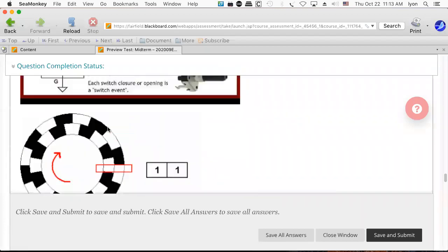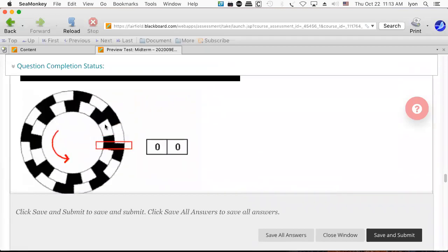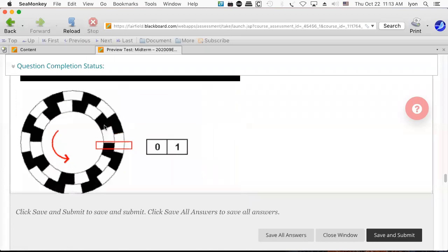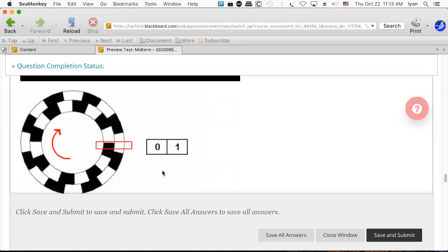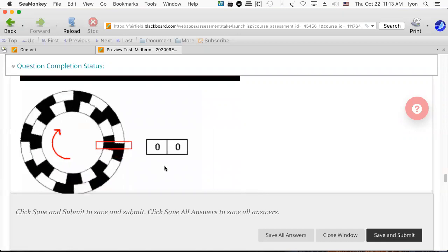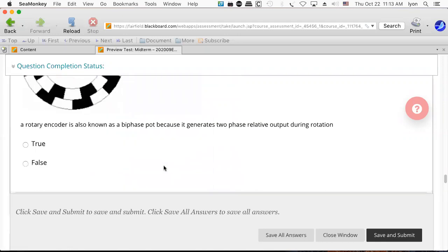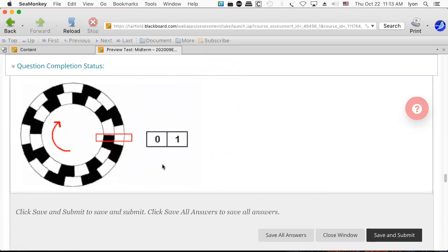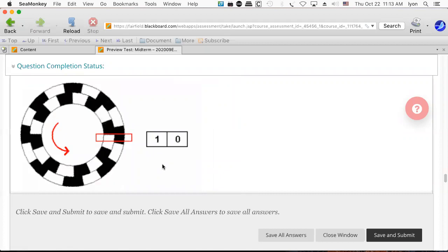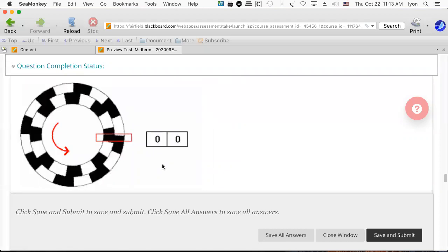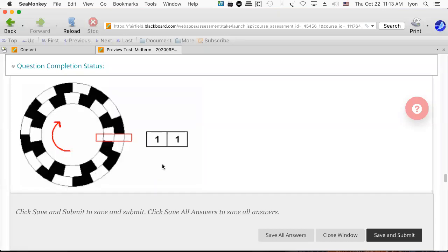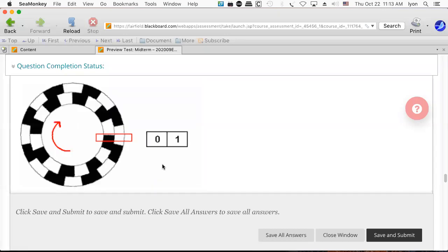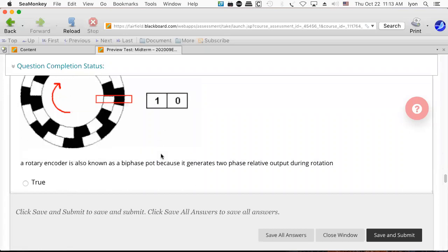And that lets you determine how many rotations you've had, or you could even be more precise and go just part of a rotation. And this will help you to keep track of it. So you can use these in robotics. In fact, we have these gray code generators associated with DC servo motors that are mounted on the joints of various electric robots that we have on campus. So that's kind of interesting.